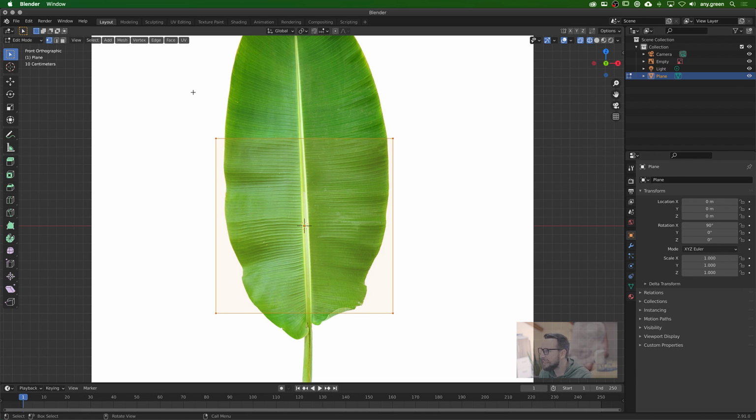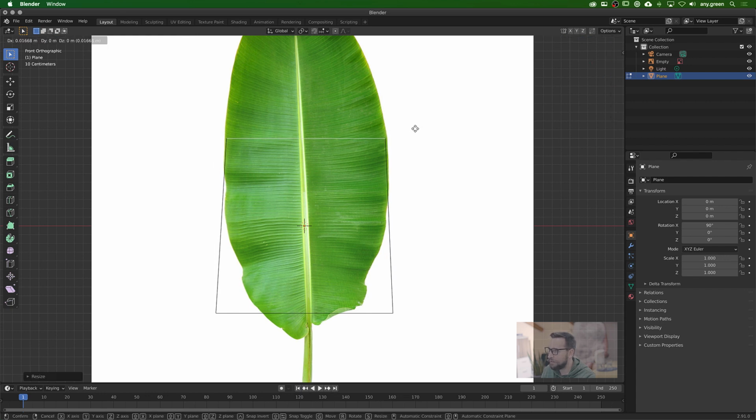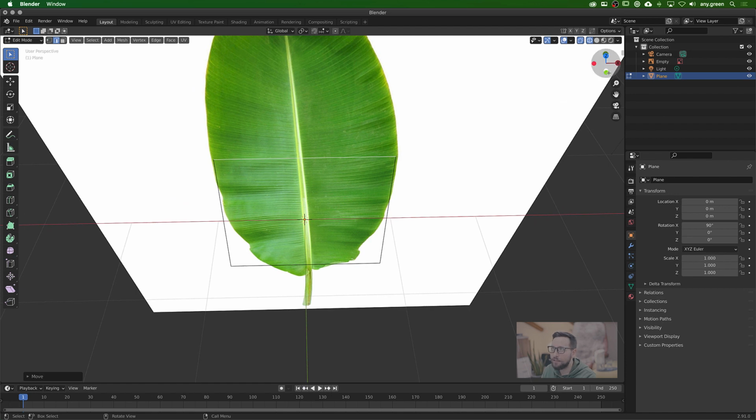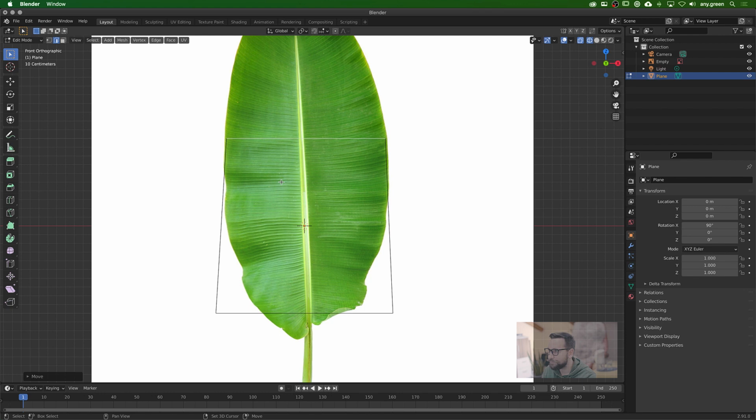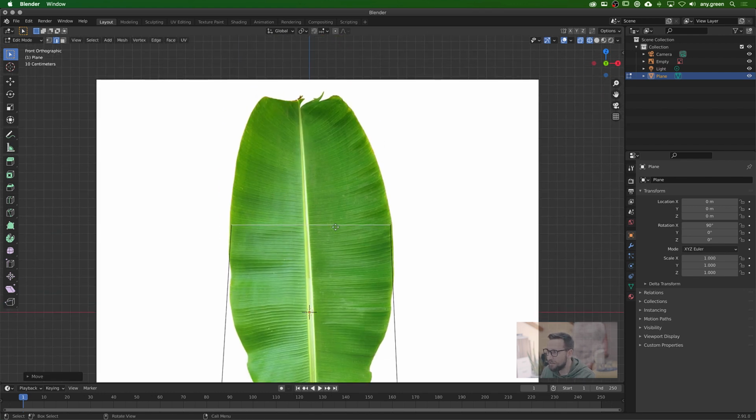All right, so let's hit edit, switch to our edge mode, and just start by grabbing edges and scaling them down, maybe moving them around a little bit until it at least roughly matches. Come on, this is the one. We can always hit E to extrude a new edge and adjust that one in the size and the position.